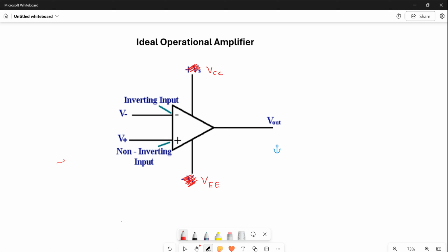Hello, I'm going to discuss operational amplifiers and the best way to analyze the circuits. Hopefully it'll give you some insight and make them a little easier for you. I'm going to start out by looking at an ideal operational amplifier, and its symbol looks like this, and it's biased with a plus voltage, which they normally call VCC, and a negative voltage, which they normally call VEE.